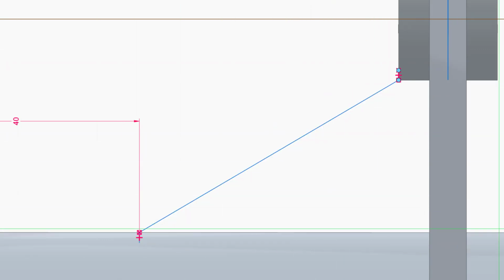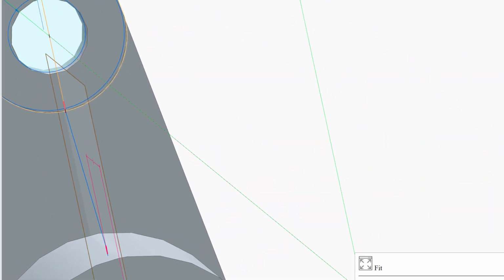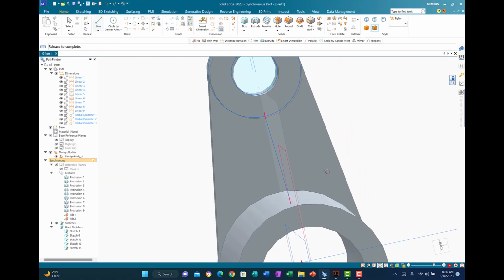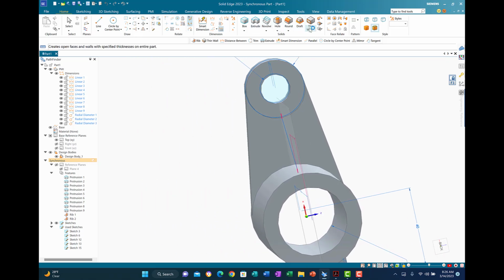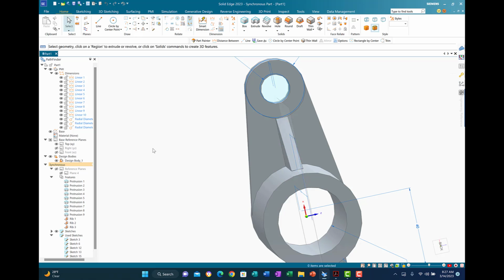What I'm gonna do now, I'm gonna rotate it. The next step is, let me bring it to the location here, to the front, to the middle. You can do it like this if you want. So I'm gonna choose thin wall, rib, and when it comes, I need to choose chain. So I need to click on the chain here, the line I just drew. It accepted, accept, and then it gives me 6 millimeter. I say accept. I'm gonna say enter, and it is done.